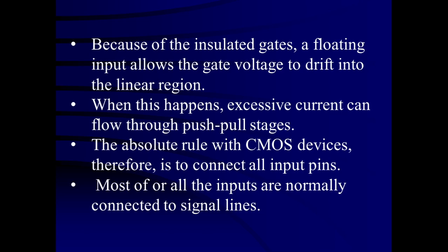The absolute rule with a CMOS device, therefore, is to connect all input pins, and most or all of the input pins are normally connected to the signal lines. So, in a CMOS device, it is mandatory that you connect all the input pins.